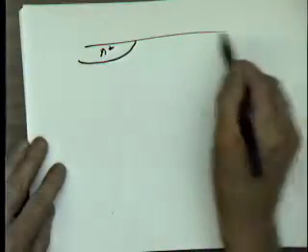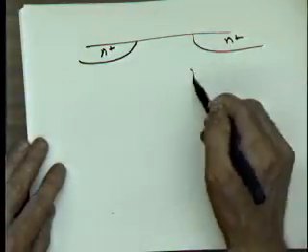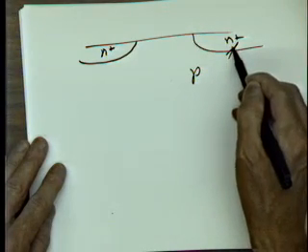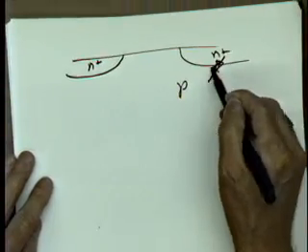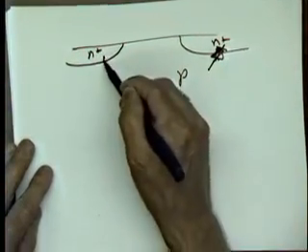There's one more question that I had regarding capacitance. The last question is about the diffusion capacitance. The diffusion capacitance, remember, is the capacitance that I get from the N plus P junctions. We have those reverse biased diodes sitting right here, and I have another diode like here.